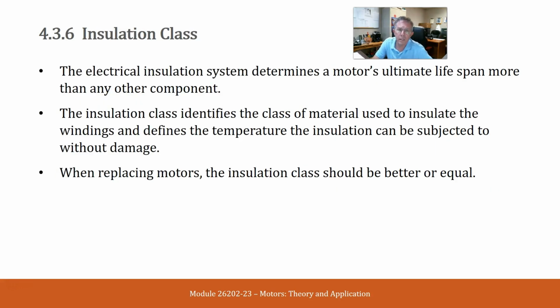Insulation class. The electrical insulation system determines the motor's ultimate lifespan more than any other component. The insulation class identifies the class of material used to insulate the windings and defines the temperature the insulation can be subjected to without damage. When replacing motors, the insulation class should be equal or better.